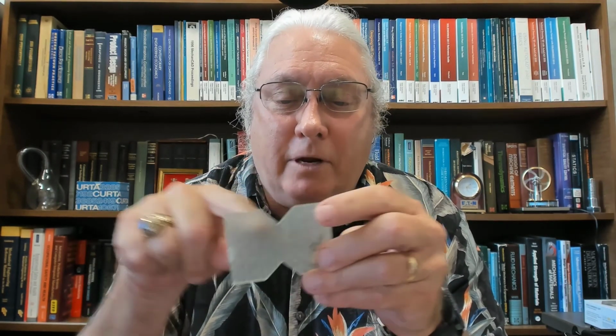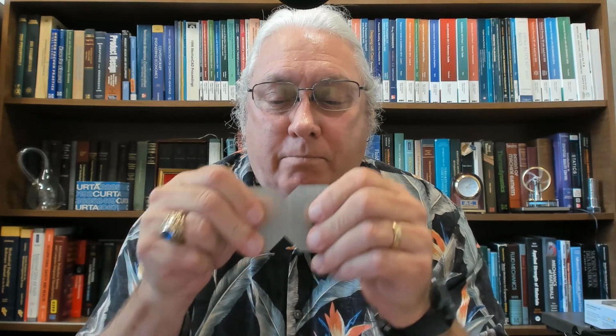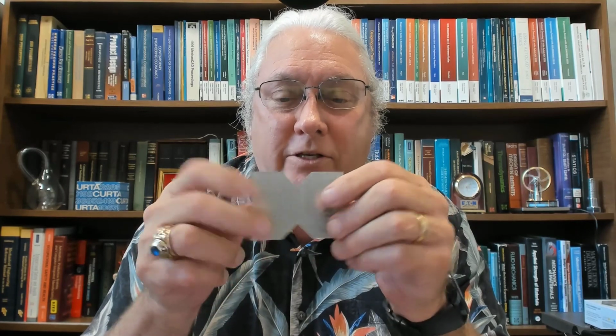But with orthotropic materials, you have those different parameters for different directions because this is a laminate. Go look at that drawing. If you didn't get a copy of that drawing, send me an email. It's got different strength properties depending on which way you're pulling on it. This is a laminate going this way and this way. So these properties going side to side and going in both directions, X and Y, are the same, but going this way is different. And if we use this material in a loading condition that's got out of plane loading, then those stiffnesses will come into play. So that's it for now.